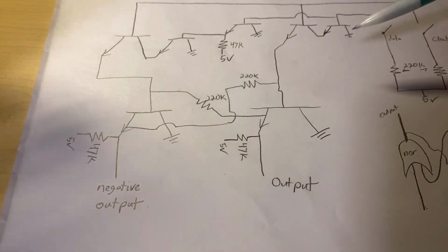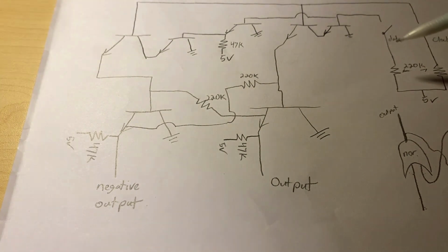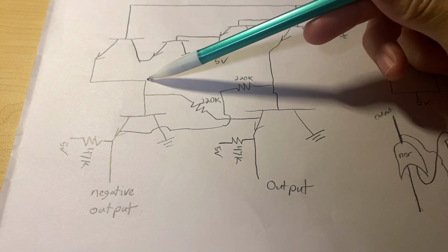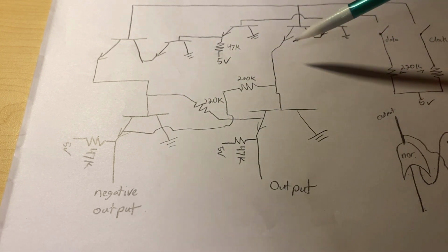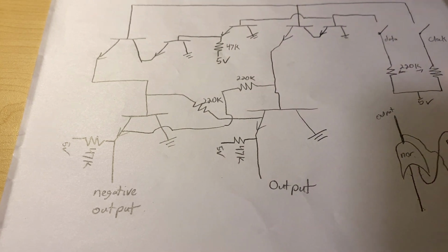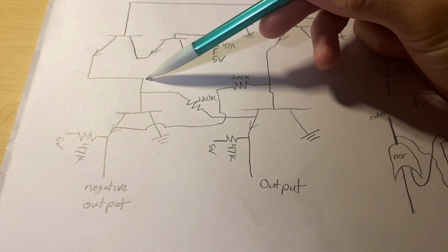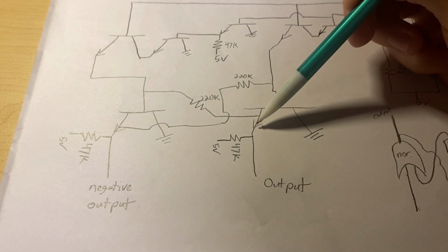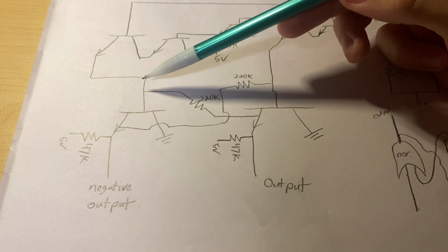So this is how the SR gate works with transistors. Bear with me because this might get a little complicated. When this area is hooked up to the ground, these inputs are kind of opposite. Once they're hooked up to the ground, that's kind of inputting the signal in. So when this side, let's go with this side first, is connected to ground, this 5-volt source goes through this resistor, travels up, goes through that resistor right here, and goes immediately to the ground.